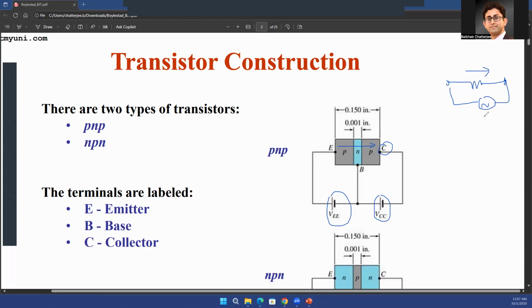For diodes, you know that the current flows in only one direction, but not in the other direction. So you have some control on the current that flows through the diode device. However, you cannot control the amount of current for a particular diode voltage. So let's say you have this diode, and you have connected some kind of a voltage across it. If this voltage is fixed, you cannot control the current that flows through the diode. You can only control the direction of the current by flipping the polarity of the voltage, but you cannot control the amount of current that flows through the diode.